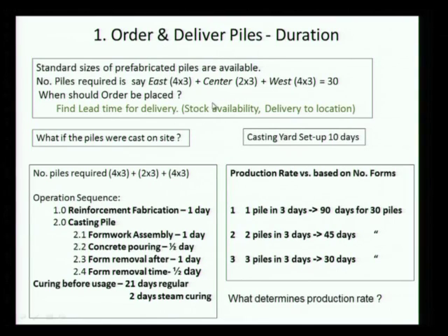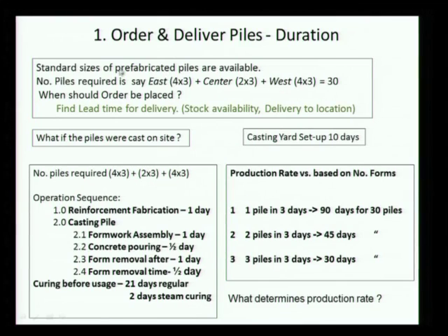Okay, so this slide is a bit busy, but let us see what we can make out as to estimating duration for precast pile. The simplest one is, if I have to order the piles, I have to decide what the lead time for delivery is. I can't go to the precast yard and say I want 20 piles and he will deliver it by evening. It's very unlikely. He will need a certain amount of time because he will have a backlog of orders. I'll have to find the lead time and then place my order based on the lead time.